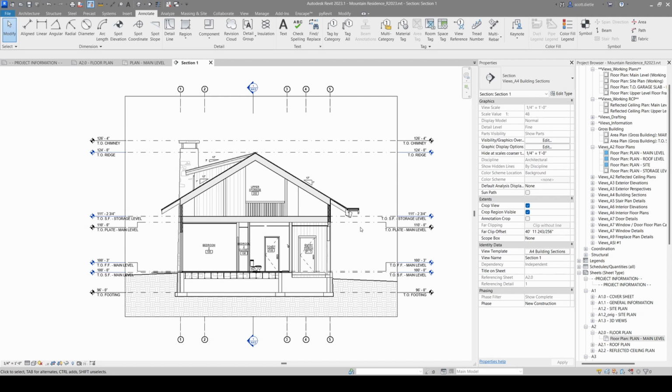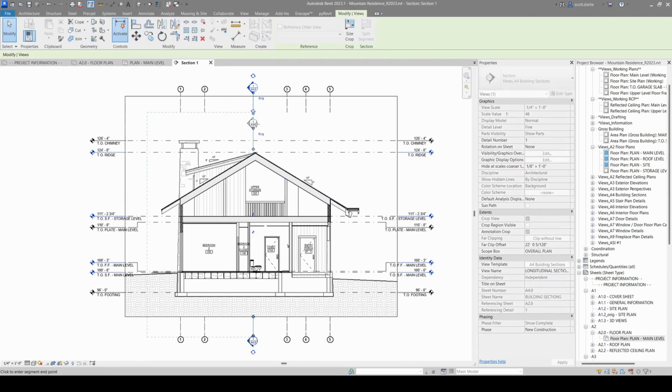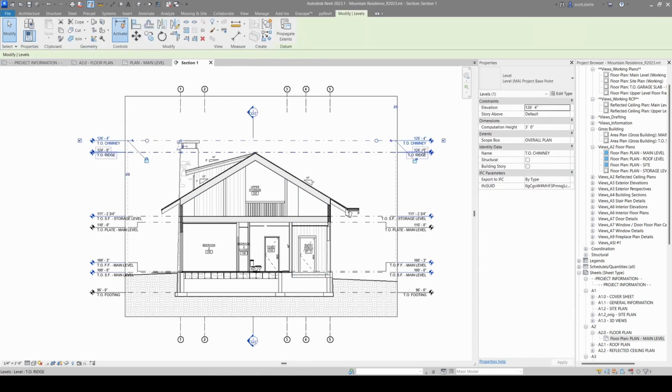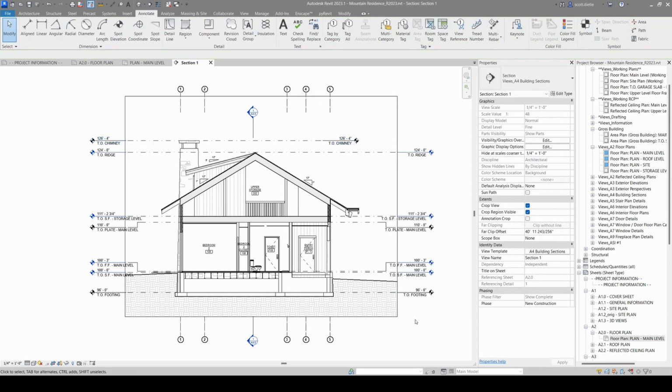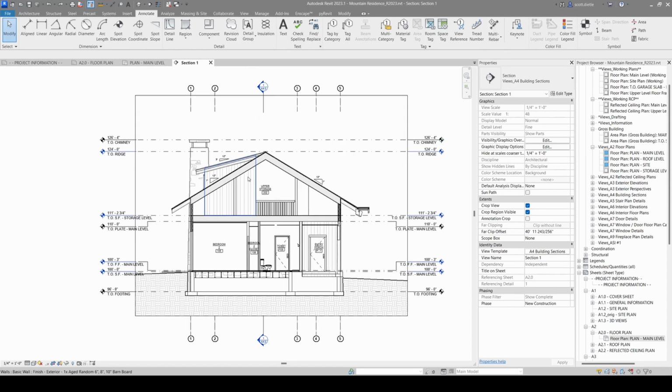If you put together a set of drawings where you've got section heads down here and you've got a grid head, you know, randomly over in this direction, it just shows that you didn't take the time to really put this together and intend for this drawing to look good. Clean things up, line up all your datum heads, line up your grid heads, make these drawings as much of a piece of art as you can.